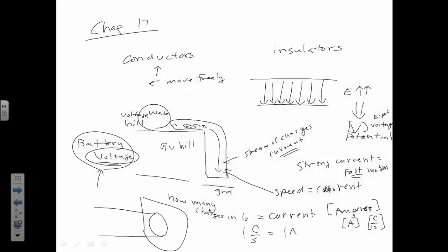But if they are not very heavily loaded, they might be 400 or 500 milliamps. Milliamps means 0.4 to 0.5 amps. If I were to hold it while I had this voltage applied to it, these things would probably pull about an amp, maybe a little more than an amp each. All right, so an amp's not necessarily a huge amount of current.